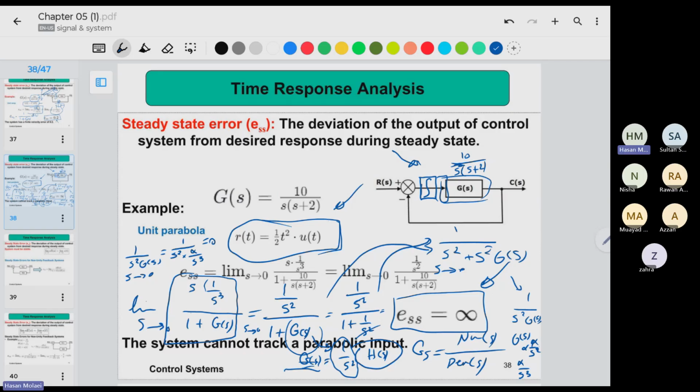You need to, because adding the integrator, basically you are increasing the number of poles, right? So it might cause other stability issues. We will consider it later. But let's say everything is still stable and you want to follow this kind of input, ignoring the other factors, just focusing on the steady state error. Then it looks like adding the integrator is solving the error problem.